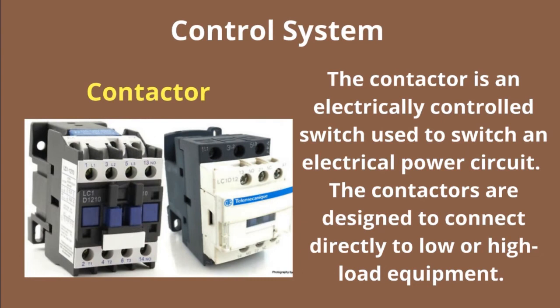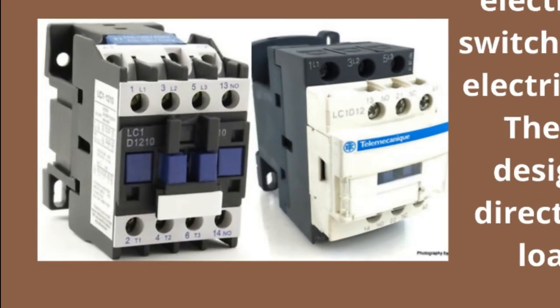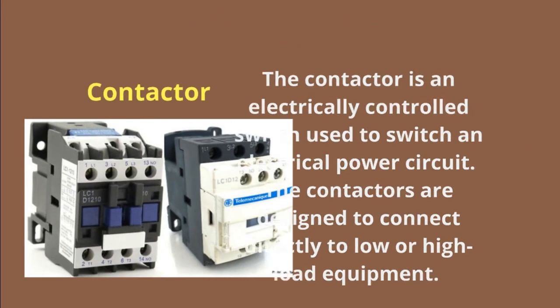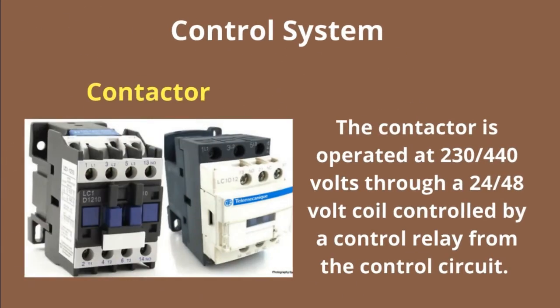Contactor. The contactor is an electrically controlled switch used to switch an electrical power circuit. The contactors are designed to connect directly to low or high load equipment. The contactor is operated at 230/440 volts through a 24/48 volt coil controlled by a control relay from the control circuit.